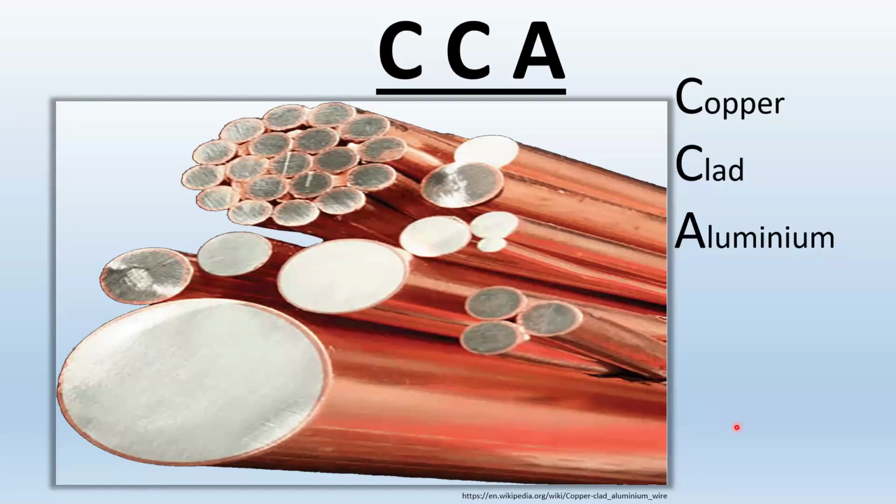If you see some box of wire, or the price of the wires that you buy when you're buying wiring, the cables, at some kind of unusually low price, check if it is CCA. And if it is, please do yourself a favor and do not take it even if somebody gives it to you free.